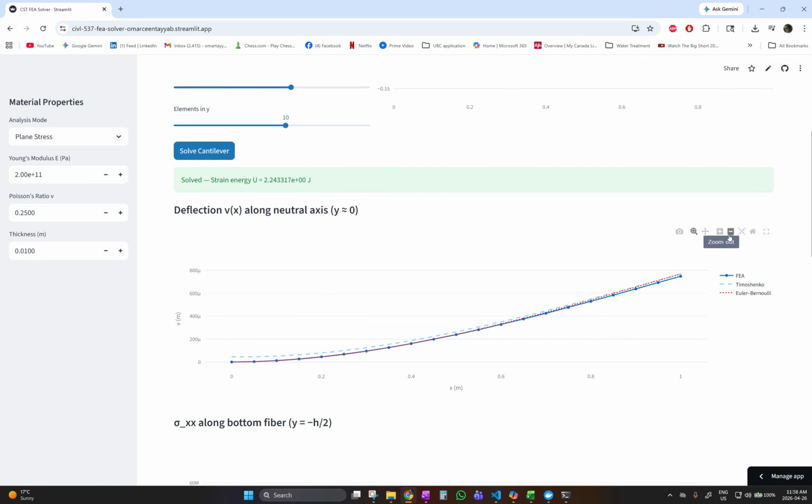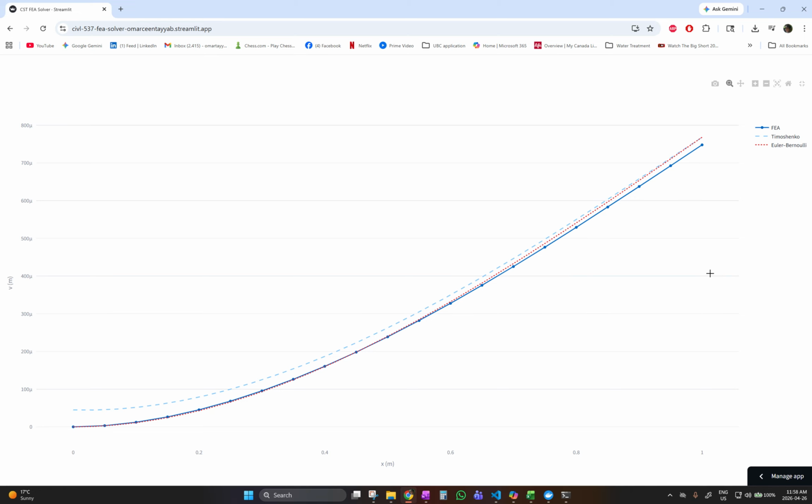Just on Euler-Bernoulli versus Timoshenko. Timoshenko does a really good job at capturing shear. Euler-Bernoulli does not capture any shear because of an underlying assumption that all plane sections remain planar, and that's just not true, right? Where is it not true? Where the max amount of shear is being applied. Where is that? At the fixed nodes.